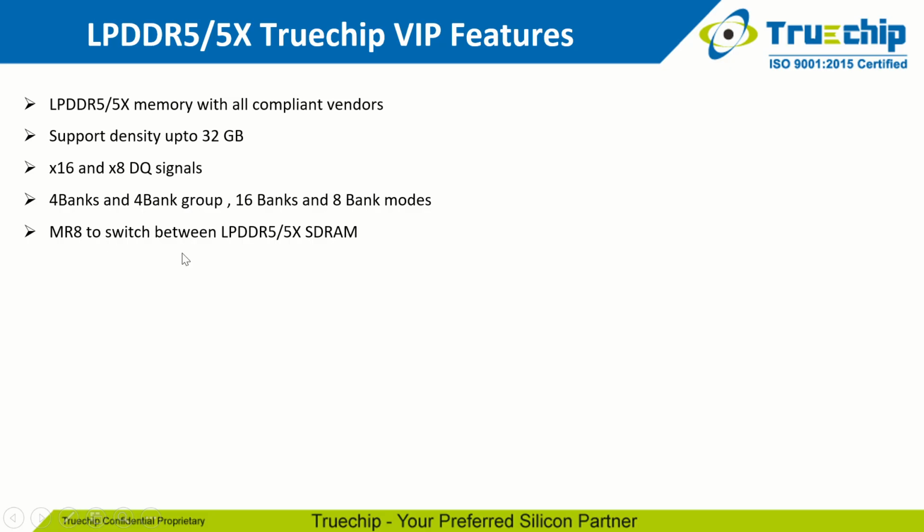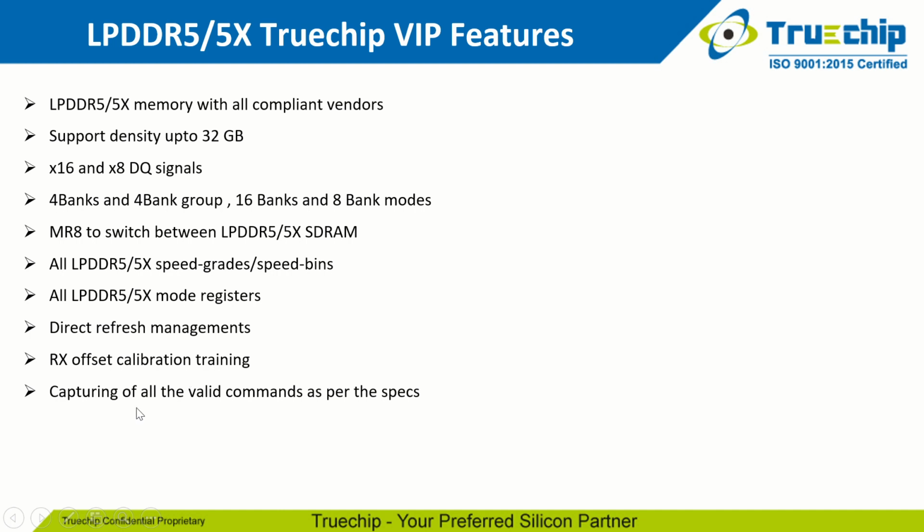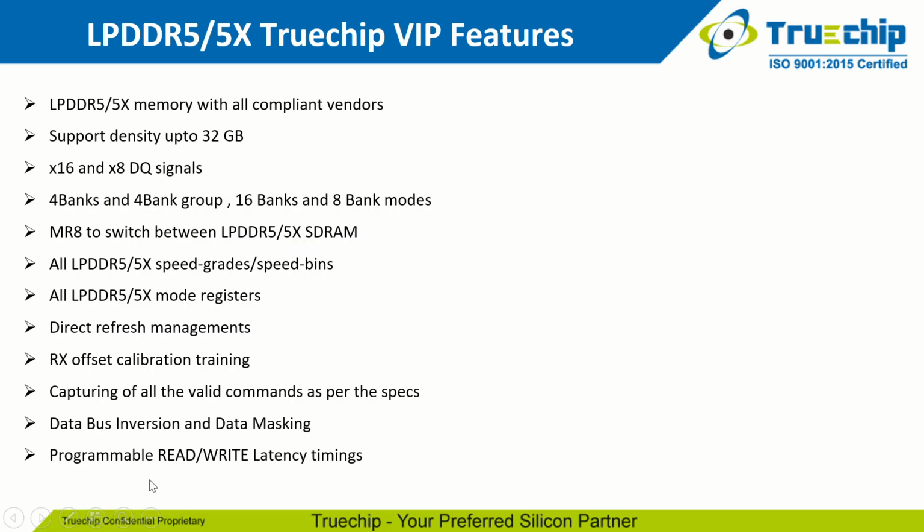MR8 to switch between LPDDR5 5x SDRAM. All LPDDR5 5x speed grade speed bins. All LPDDR5 mode registers. Direct refresh managements. RX offset calibration. Trainings. Capturing of all the valid commands as per the specification. Data bus inversion and data masking. Programmable write read latency timings.